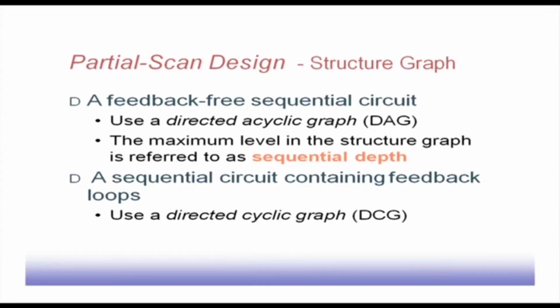Here we look at the structure graph, a feedback free sequential circuit. That is what we are looking for. For that purpose, first of all we construct a directed acyclic graph. The maximum level in the structure graph is referred to as the sequential depth. I think there is an example.